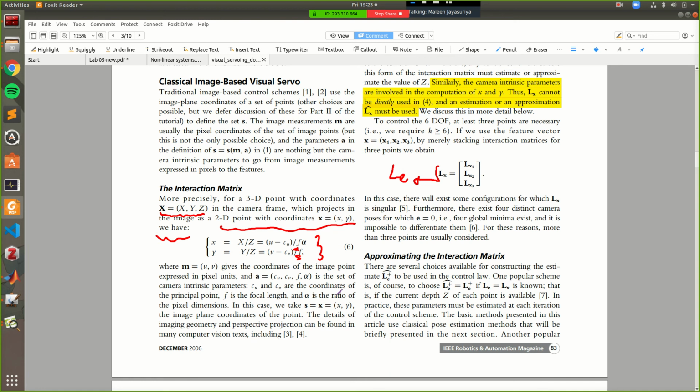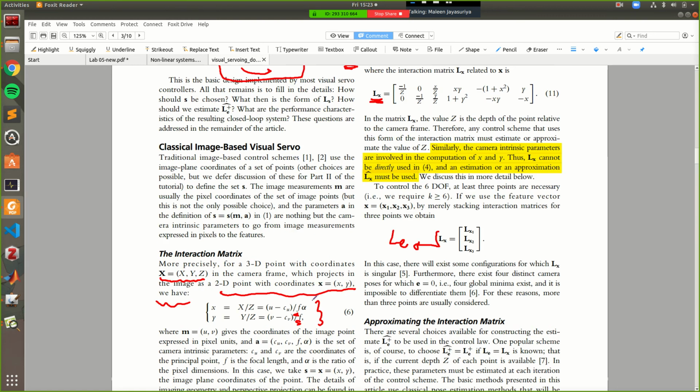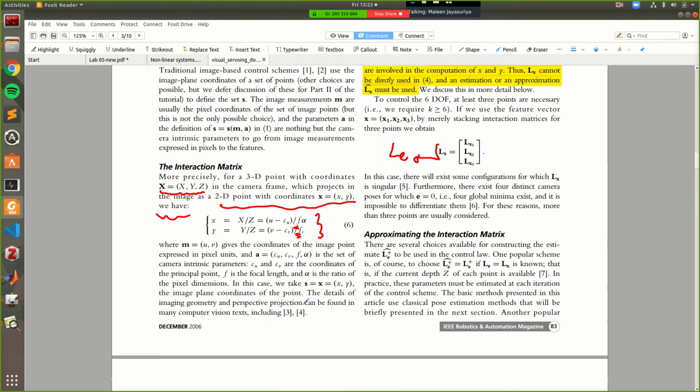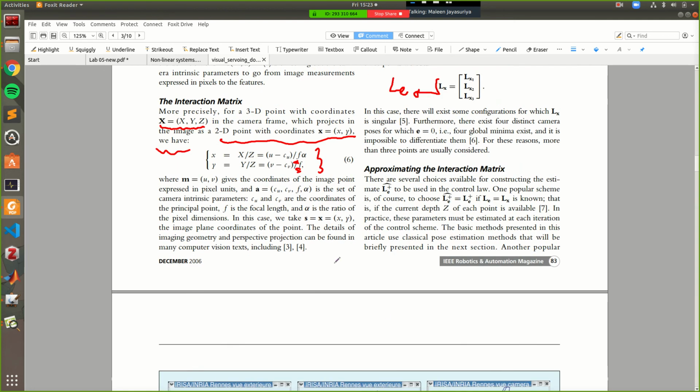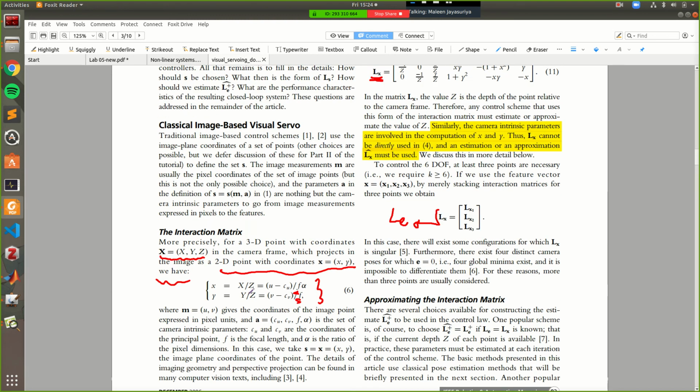There's a lot of noise. All of these equations are just approximate models of the real world. They don't take into account all the random noise and issues in the motors and in your sensors. So you implement something like this, and then you add other heuristics to control it. You tune parameters so that it ultimately does what you want it to do.